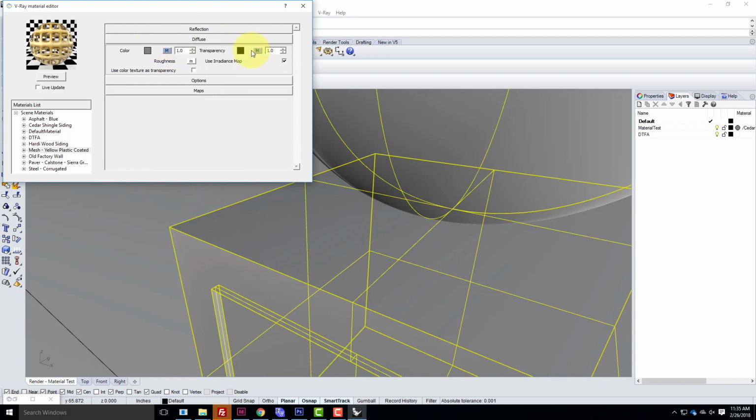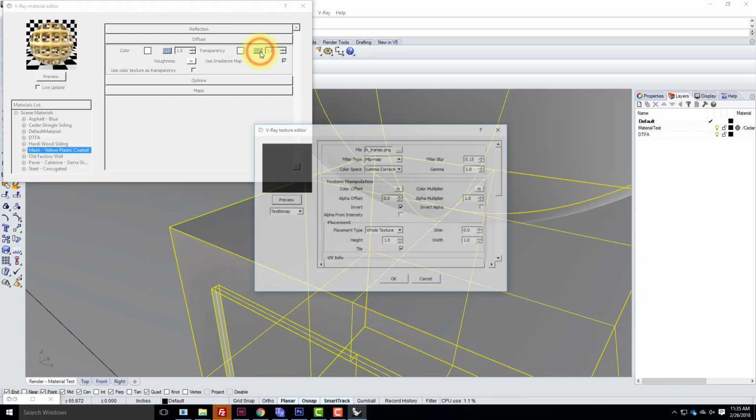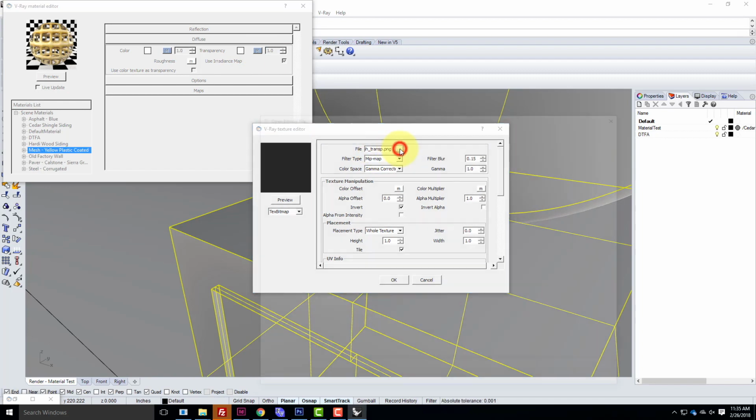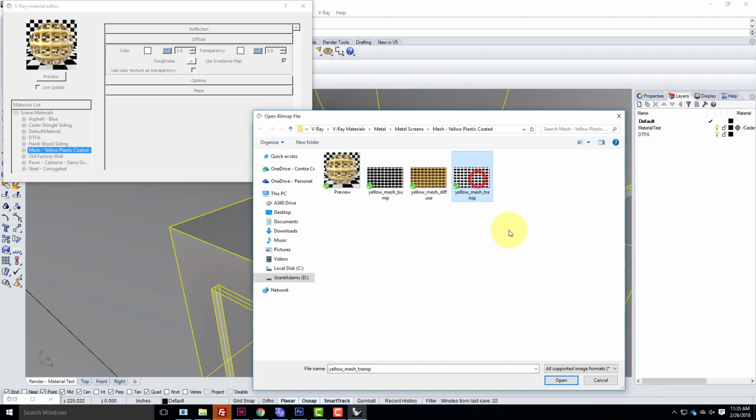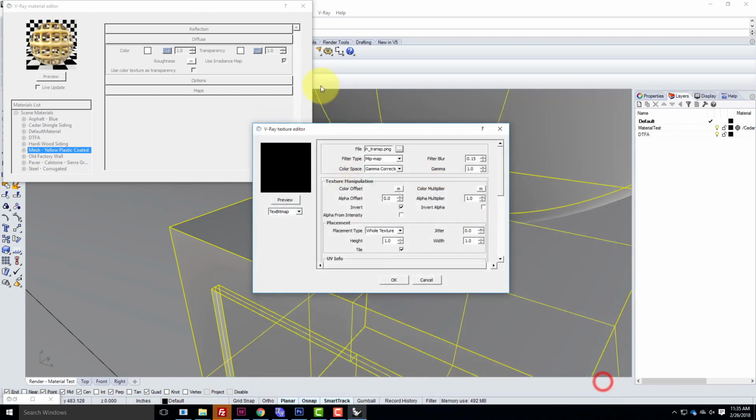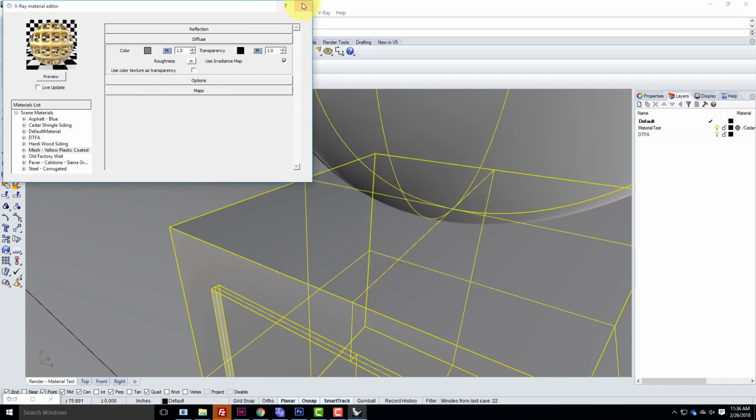The other option, though, is opposite the diffuse. This is the photo, is transparency. And you guys have adjusted the transparency prior to now by just adjusting the color value of this transparency. So black being solid, white being transparent. If I look in here, I've used a transparency map this time. So there's my transparency map, just black and white. And if we preview it, I did it backwards again in that original file, so it's checked for invert. And so there it is. That represents what's cut out. I can say OK. Now when I go to render it,